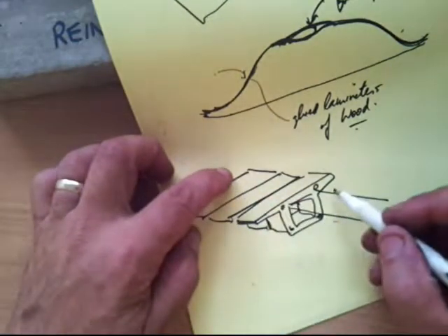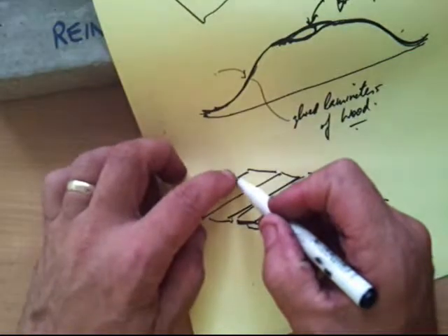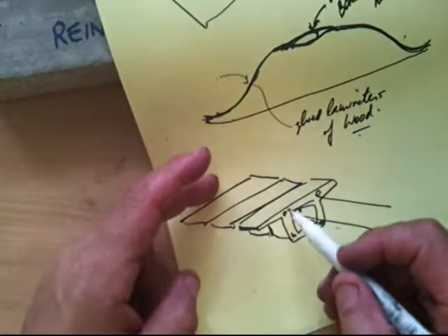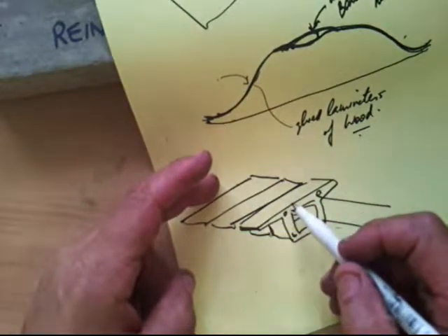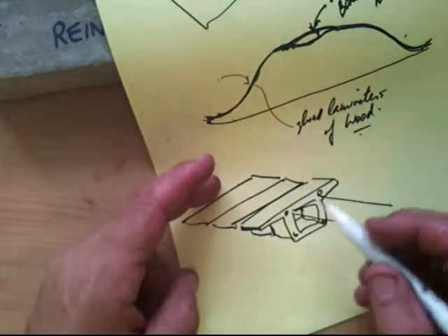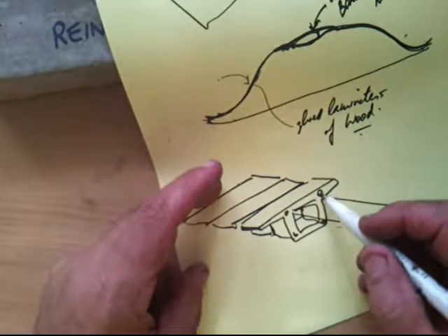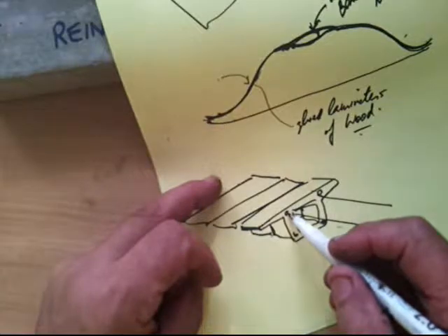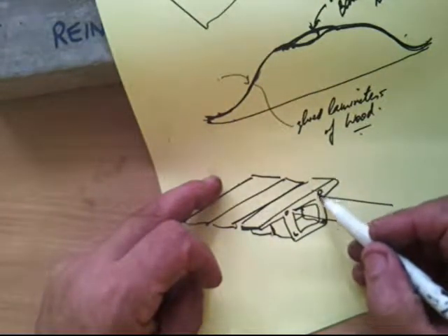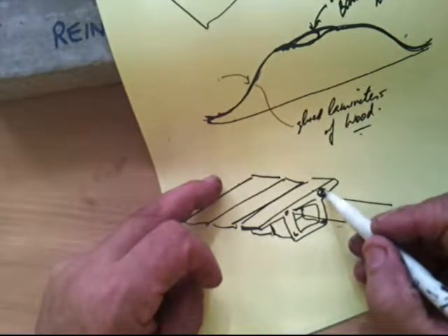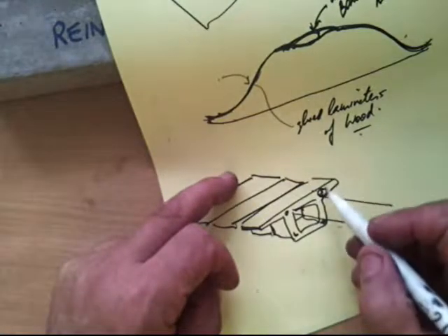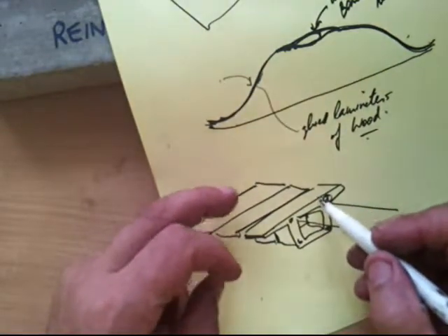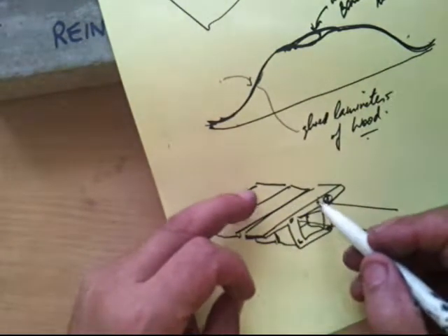then tendons or metal bars are run through these holes, and then a hydraulic machine will fix them at one end, crimp them at one end, and then tense them at the other end, pushing the whole group of modules together very strongly. And then once they're under tension, concrete will be poured inside these holes to be able to keep the whole thing stable. Then a hydraulic machine will seal off the end, and then the remaining reinforcement bar will be cut off.